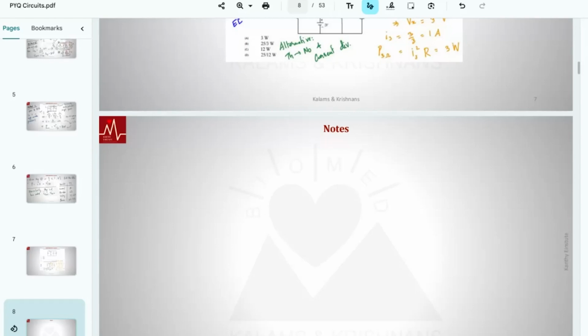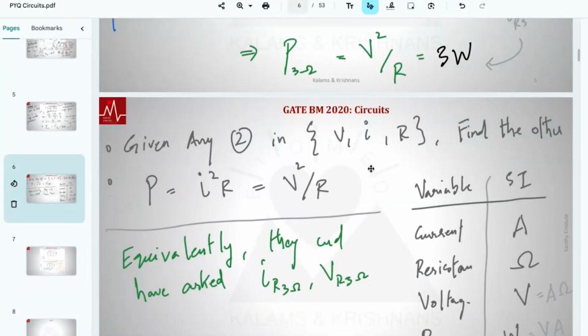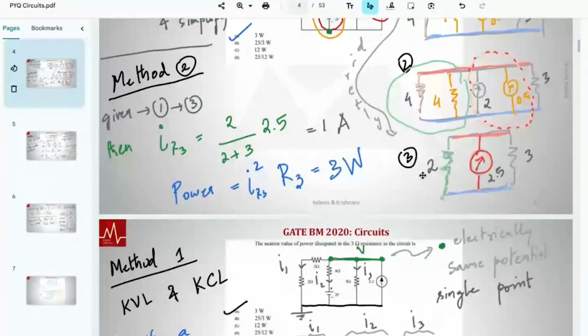Look at the top: is it all one wire? If it's all wires at the top, it's probably a single variable problem. Wires at the top and wires at the bottom are a sure sign of a single variable problem. This mix of sources, potentials and amperes, hints at source transformation. There's one long green wire at the top and one long wire at the bottom, so likely there's one variable. If I solve for it, I'm done.